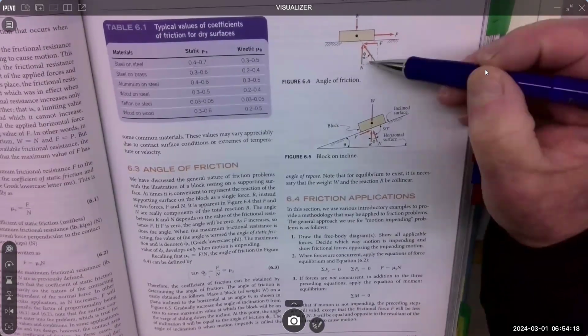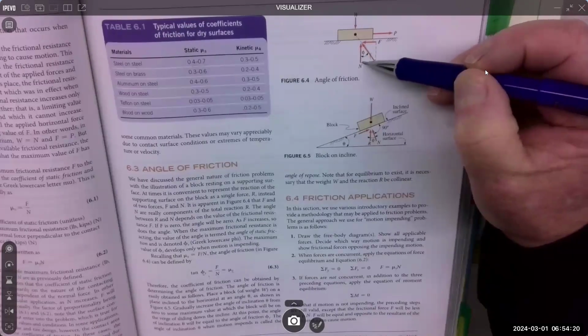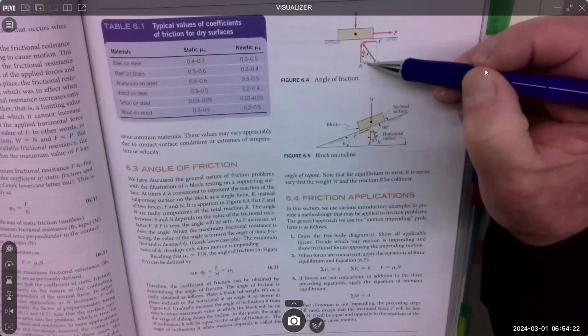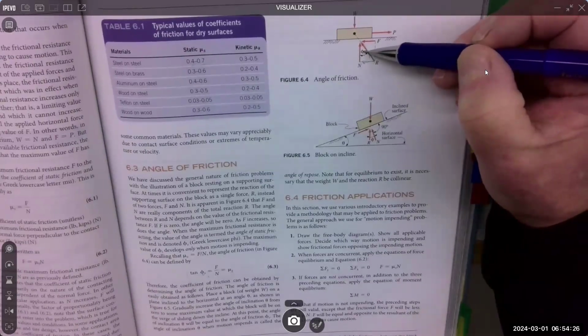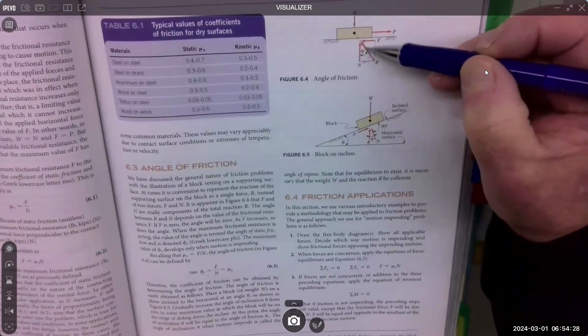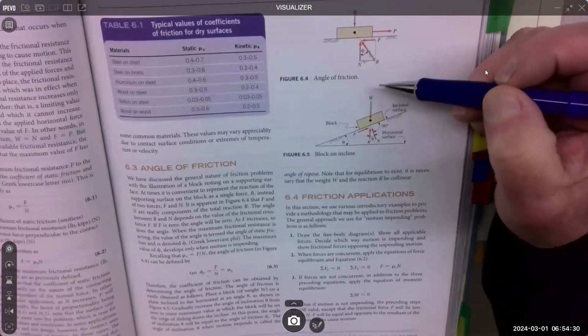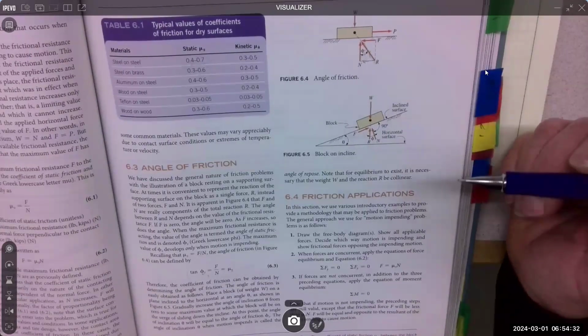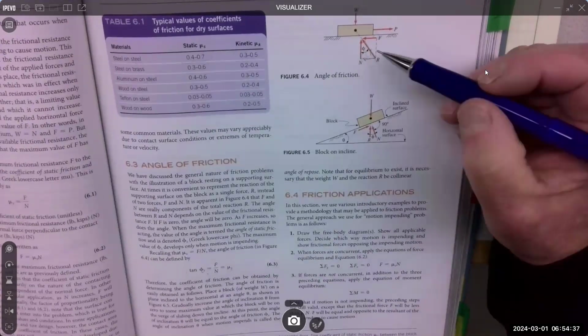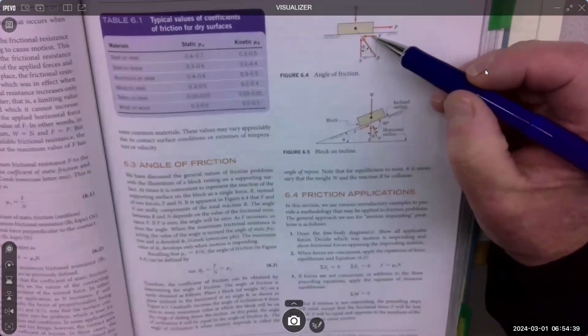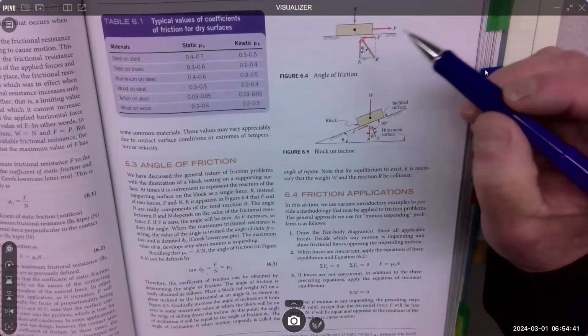So, you know, trigonometry, F is here. You can see why we use tangent. Tangent is F over N. This is the static angle of friction. This gets drawn in the maximum friction force condition. So you can't come up with calculated friction from this. You can come up with maximum situation, maximum.